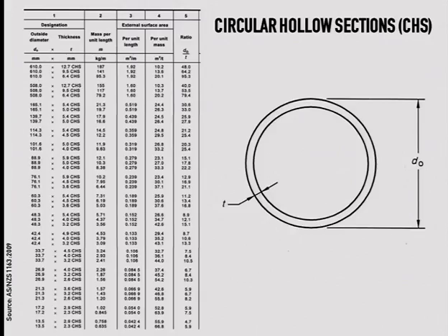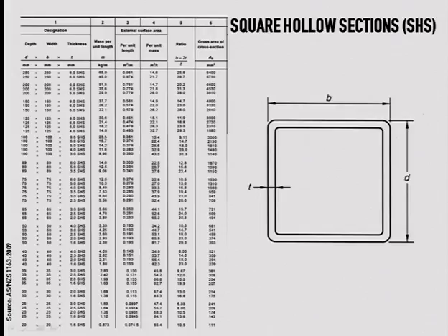Out of that, again, a few standards. Just please memorize a couple of them. Circular hollow sections, CHS. And of course we've got the square one. You see that because of folding, that's the type of fillet again we get in the profile. You remember that before with the hot formed one, the profile was sharp at the corners, not in the web but at the corners.